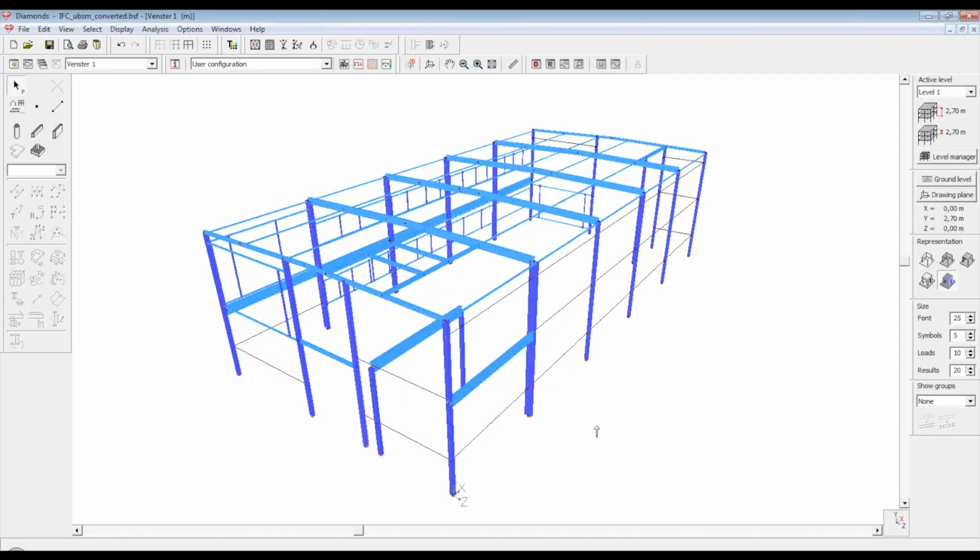Another possibility is that you use the control button. You hold the control button down, you click once on one of the lines with no cross section, and all of them will be selected at once, because these elements are stored in a certain layer, so these are easily selected.